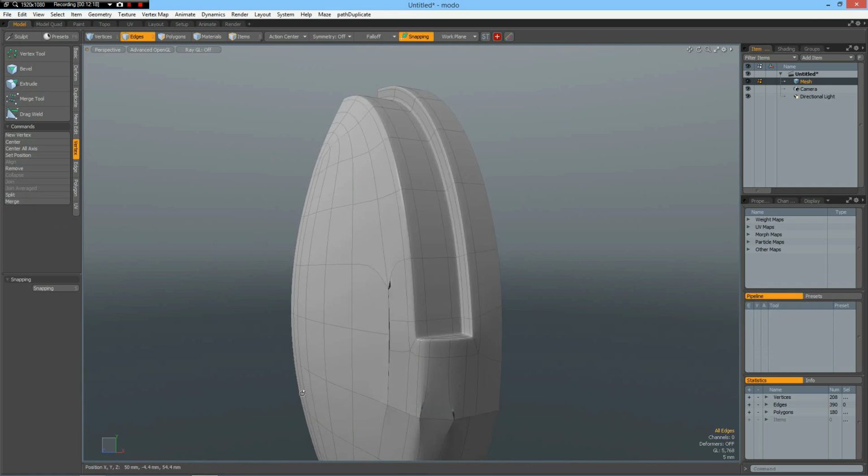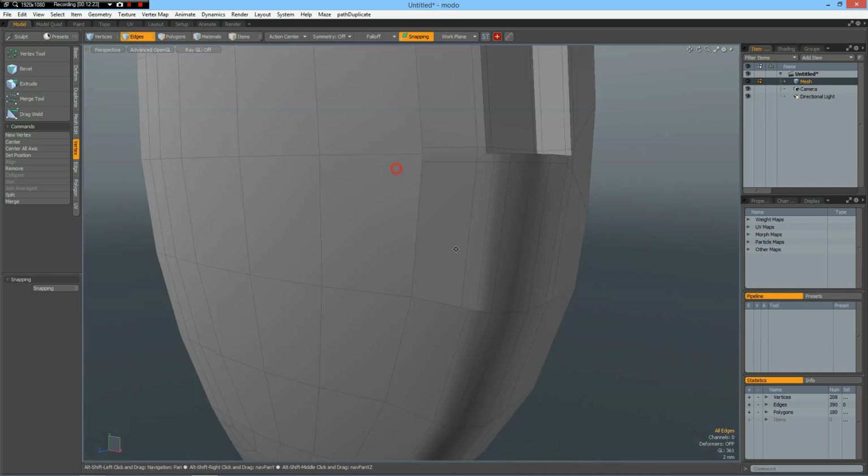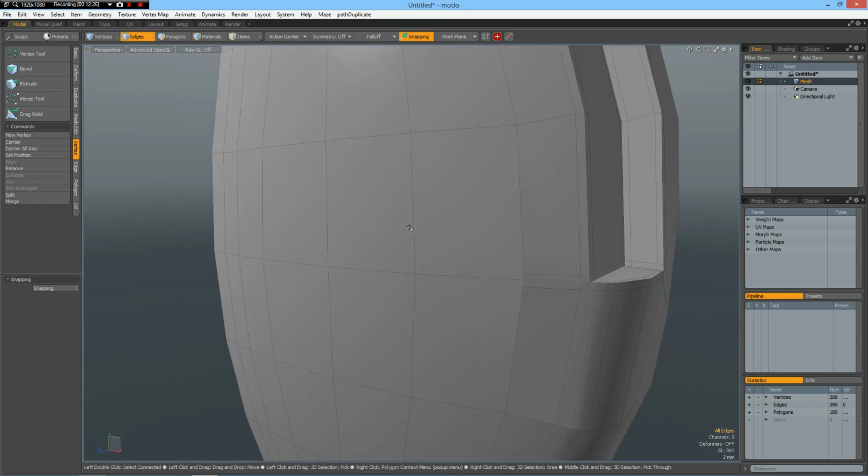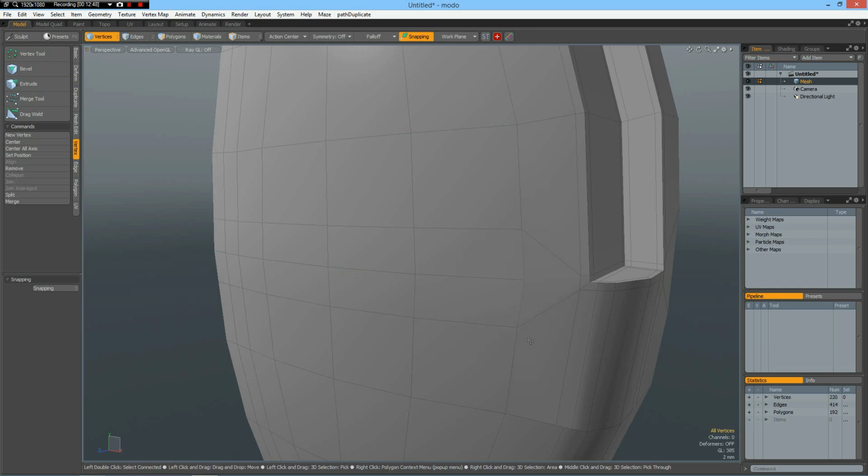Some have merged, others have not, and now we must fix this here. Now first I start up here. I put an edge in here with about 33 and here with about 66%, so we have thirds, and I can move this one to here, this one, come on, to here, and then we can remove these middle edges.